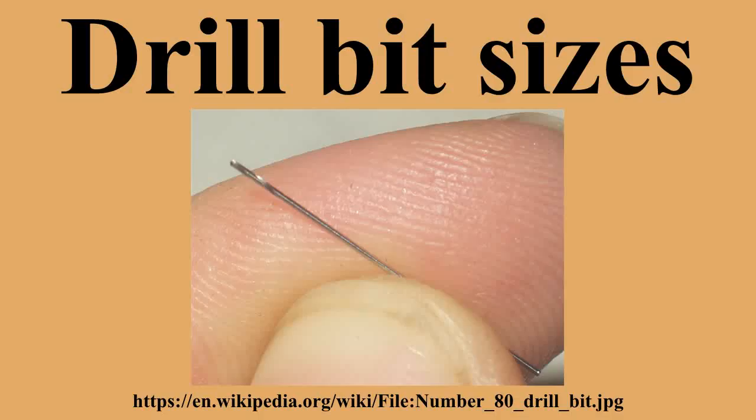Drill bits of the less routinely used sizes, such as 2.55 mm, would have to be ordered from a specialist drill bit supplier. This subsetting of standard sizes is in contrast to general practice with number gauge drill bits, where it is rare to find a set on the market which does not contain every gauge.